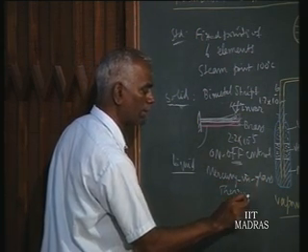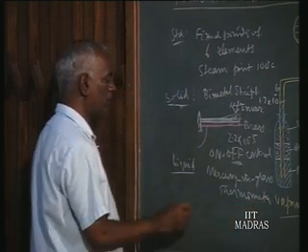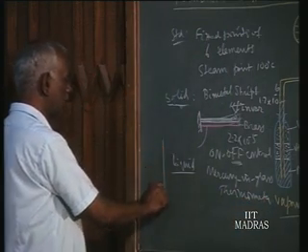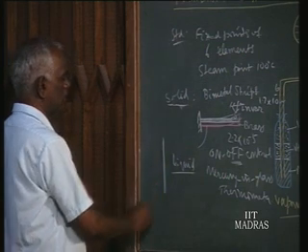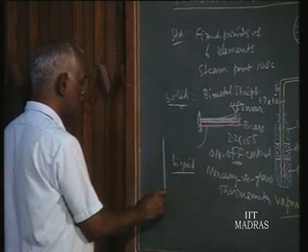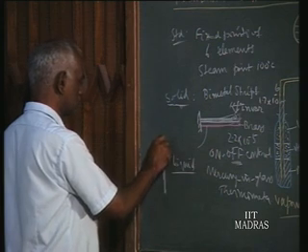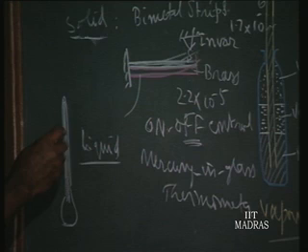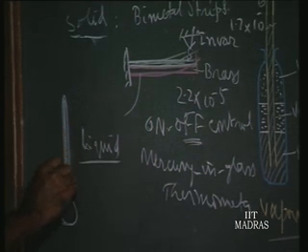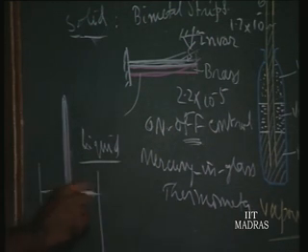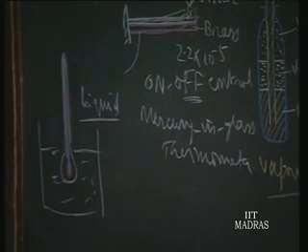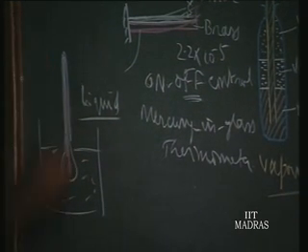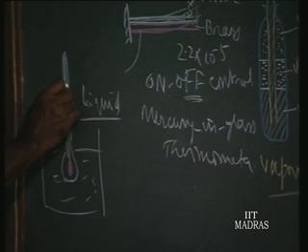thermometer. Mercury in glass thermometer. That is well known. We have a capillary in a glass material. It may be going up to here. So this is a glass column, and at the bottom we have the bulb. So you find the mercury is rising in the capillary. So mercury is kept here. It is a container, a small bulb, and when the whole thing is immersed in any bath, you find the mercury in this bulb expands and rises over the capillary column, and this is being calibrated in